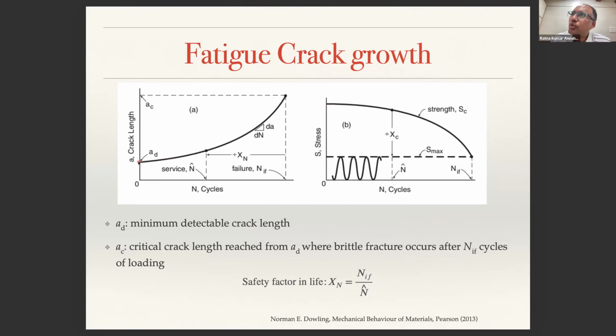Now, as you increase the crack length, what happens? Suppose your stress intensity factor K, how is it defined? How is stress intensity factor K1 defined? It is sigma root pi a, where sigma is the applied stress. If the crack is propagating, that means the crack propagates when K1 is equal to K1C, the fracture toughness, right?